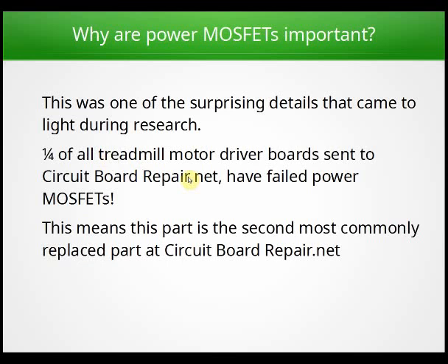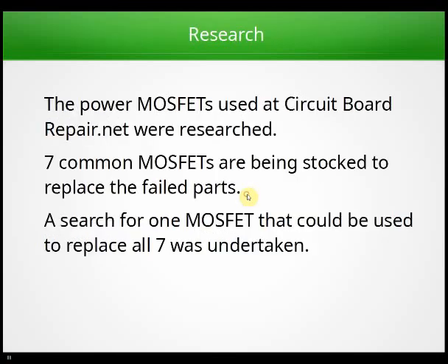Why are power MOSFETs important? This is one of the surprising details that came to light during research. 1/4 of all treadmill motor driver boards sent to circuitboardrepair.net have failed power MOSFETs. This means this part is the second most commonly replaced part at circuitboardrepair.net.